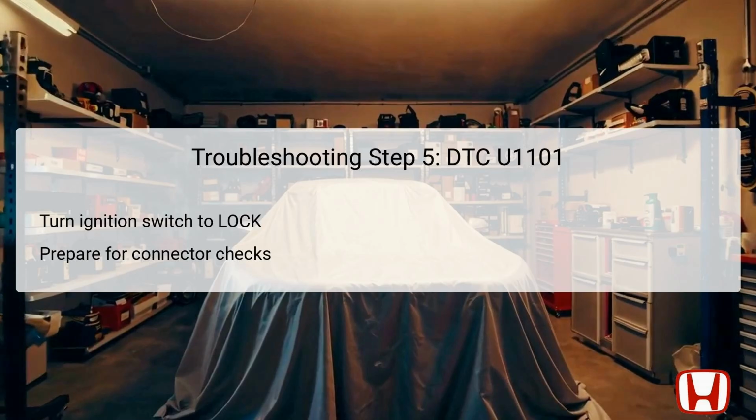It also prevents any accidental shorts or erroneous signals from affecting the diagnostic process. Once locked, the technician should be prepared for further examinations of the electrical connectors associated with both the PCM and the engine mount control unit. Ensuring proper handling during these actions is key, as they make way for effective continuity tests that will ultimately determine the integrity of the connections involved with the malfunction.